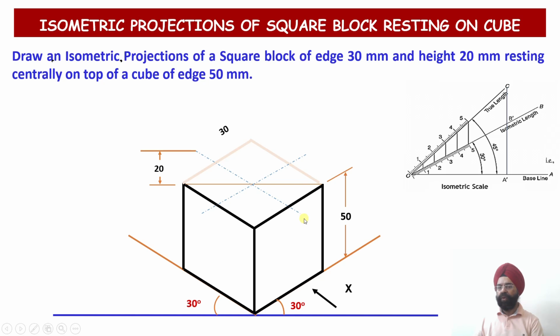So once I take out the center, and how do I take out the center? Please check. Take this dimension and mark the 50% bisector of this. Take this edge and mark the bisector point of this particular edge. Draw this axis line over here. Similarly, take this edge on the top face of the cube, mark the bisector. Take this edge on the top face of the cube, mark the bisector or the midpoint, draw another axis line.